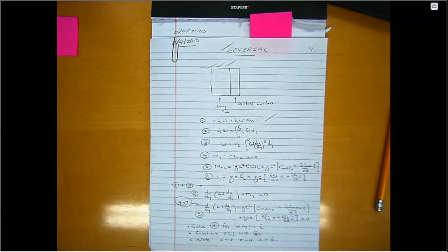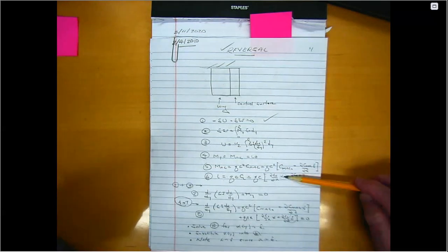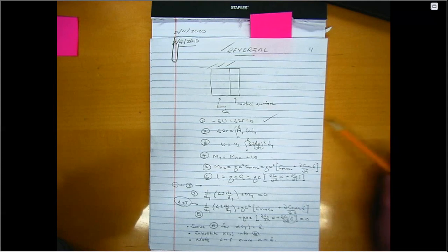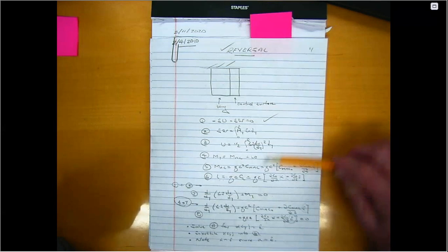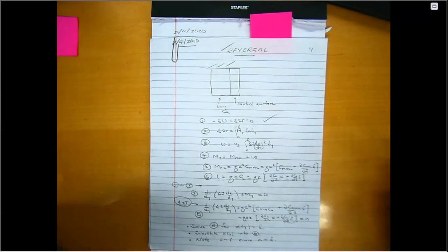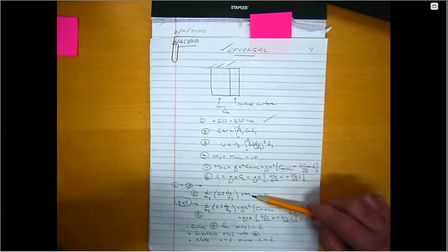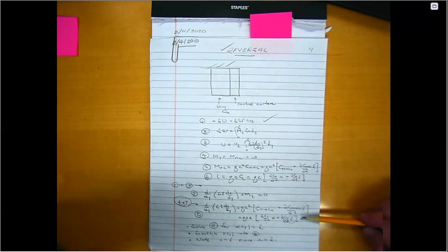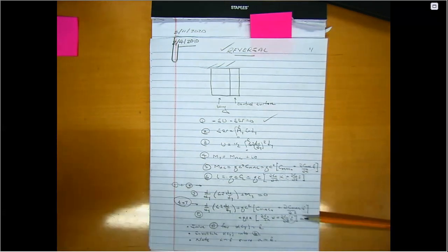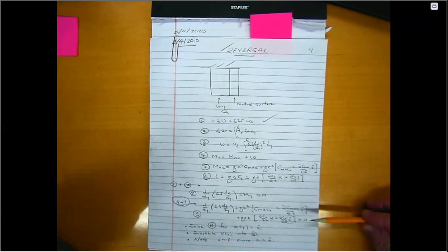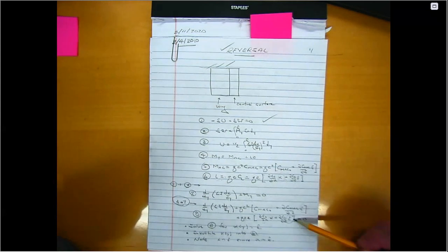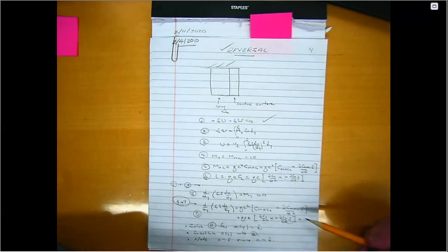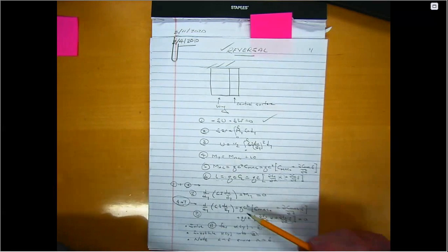And first of all, we have to find alpha, because if we don't know alpha, we're never going to find the lift, right? So how do we find alpha? Well, we write down the equation of motion, which comes out of all this wonderfulness, right? We had that before. Then you substitute in the expression for the moment about the elastic axis, which means this is all expanded now. And now what is this? This is a differential equation, which if you tell me delta, or I pretend that for the moment I know delta, then I can solve for alpha.